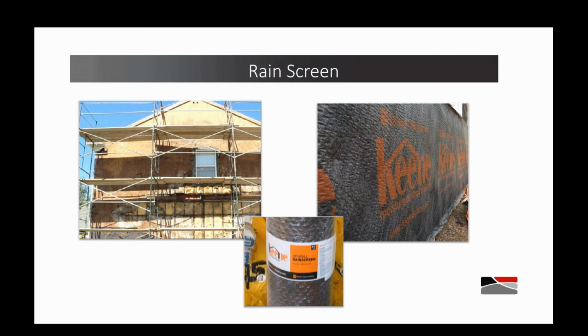And also, just on a logical level, using a material like wood to create a cavity that has to stay dry and drain rapidly seems counterintuitive, because wood by its very nature needs to hold and absorb moisture. But we are seeing more and more rainscreen everywhere now, because it deals with any moisture that gets into the building, rather than trying desperately to defend against it coming in. We still design to try and avoid moisture penetration, but also acknowledge that if it gets in, it does need to be managed.